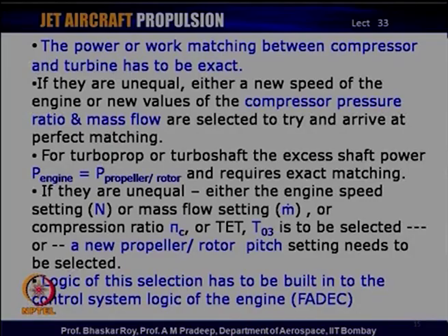Again, if they are unequal, either the engine speed will settle down to a different value, or the mass flow setting will go on to a different mass flow, or the compression ratio or the turbine inlet temperature are to be newly selected, or when you have a propeller or a rotor, a new propeller or rotor pitch setting needs to be selected.